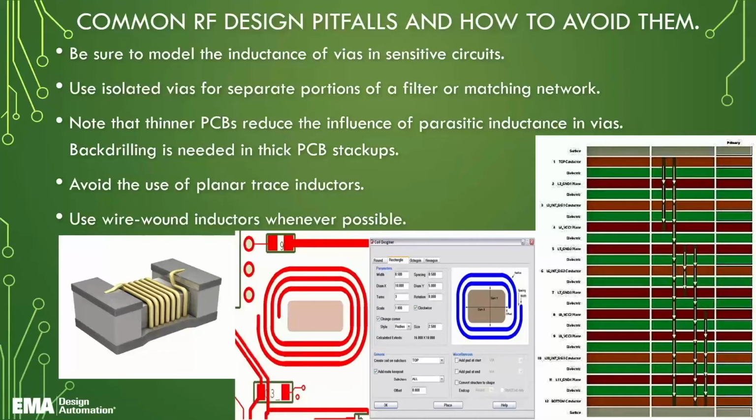Remember, if you're doing that back drilling, they've got to knock that pad out, so they're going to drill it even larger. Now it becomes a new spacing requirement as you back drill, because you're drilling that pad out, you're using a larger drill to knock that pad out. A lot of people will forget that I need that extra spacing because I'm going to do some back drilling.